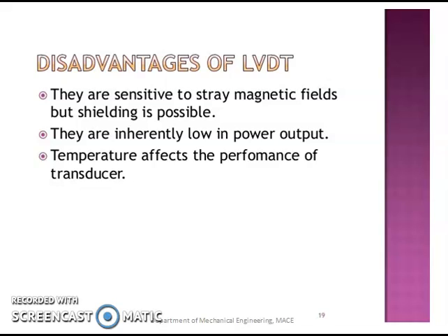It also has some drawbacks, like it is very sensitive to stray magnetic fields, but it can be avoided by proper shielding. Another drawback is they are inherently low in power output. And one more disadvantage is the atmospheric temperature will affect the performance of the transducer.